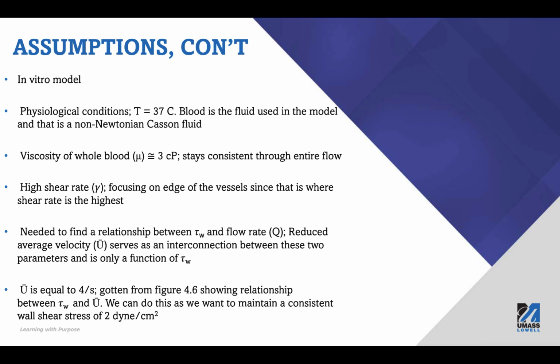So the remaining assumptions that we made in this study was that there is high shear rate, focusing on the edge of the vessel, since that is where shear rate is the highest. And one big challenge that we encountered in the model is how we can account for the flow rate change with the associated wall shear stress of two dynes.